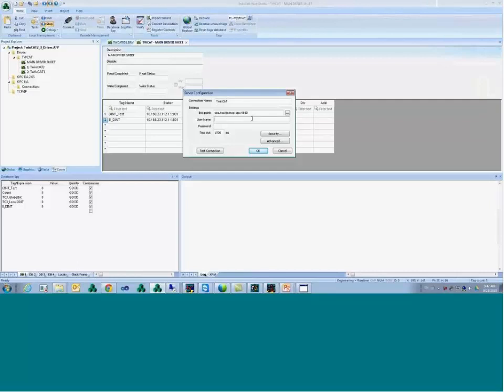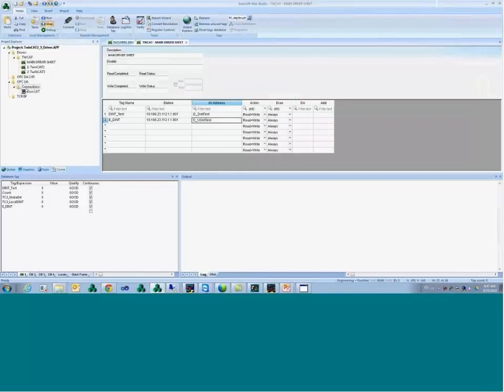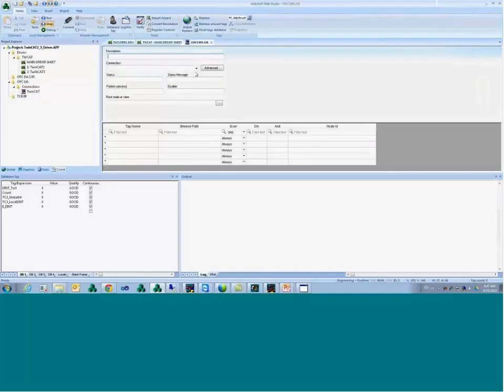But that's the basic configuration. Once you have the connection created, you give a name to it, you have the endpoint, test connection. You're good. You would go and create OPC worksheets, set the connection here, and then you can browse to the items that are configured on the OPC UA server and associate them to our tags. That's how, technically speaking, the communication would happen.